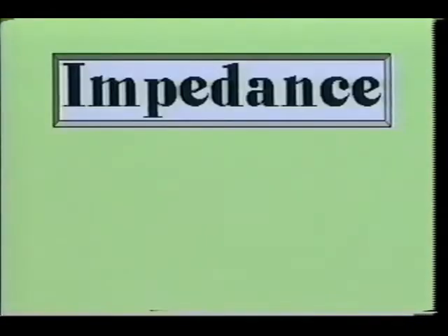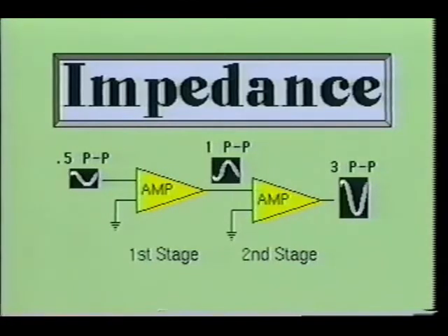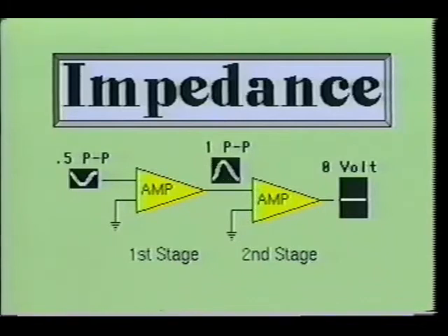The amplifier's input and output impedance is another important circuit characteristic. The amplifier receives its input signal from a prior circuit called a stage, and it delivers its output to a succeeding stage or a load device. The amplifier receiving the signal must not present too much of a load to the signal source, which may be another amplifier's output. If the load becomes too great, the signal source will be unable to provide enough signal power to drive the amplifier input, and the amplifier's output will be pulled down to zero.